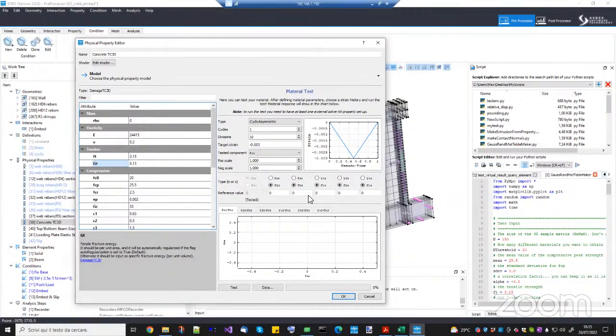You mentioned that when the rebar is embedded in the concrete, in the solid, the node of the rebar follows the displacement of the solid that is obtained as a weighted average of the nodal displacement, right? Exactly. So I understand this, but then you added that you add another constraint about the rotation. Exactly. Is it redundant or partially redundant? Can you comment on that?